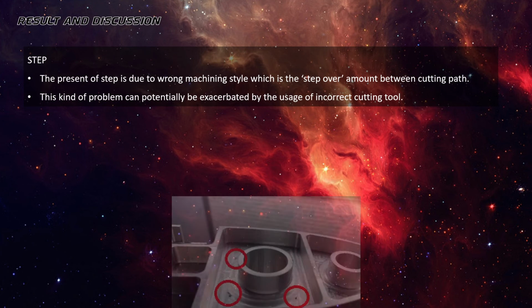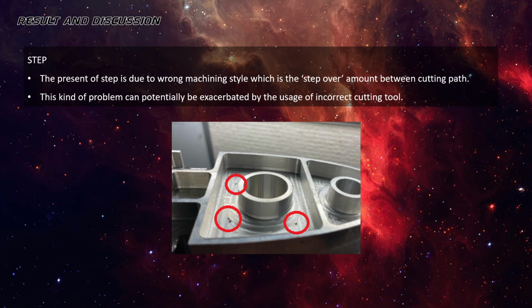Next, we also found out that the surface of our product has steps. The presence of steps is due to the round machining style, which is the step over amount between the cutting passes. This kind of problem can potentially be exacerbated by the usage of incorrect cutting tools.